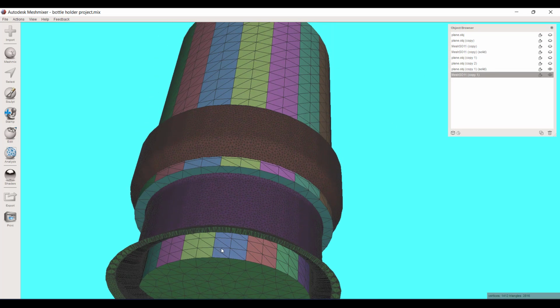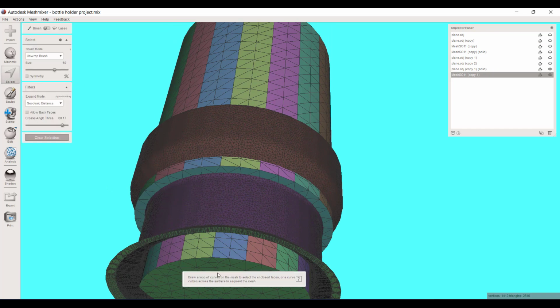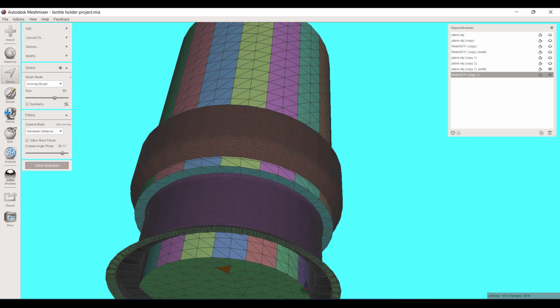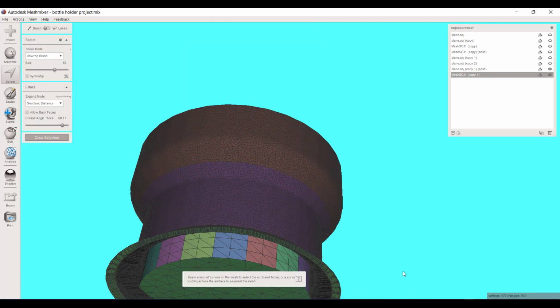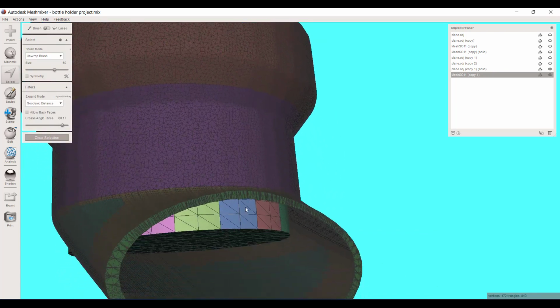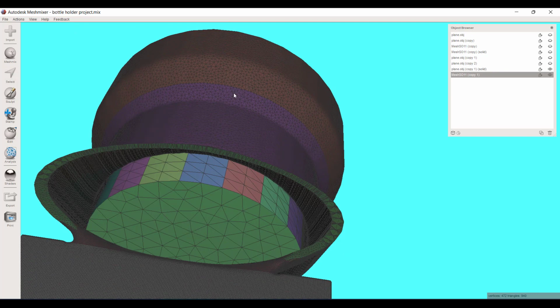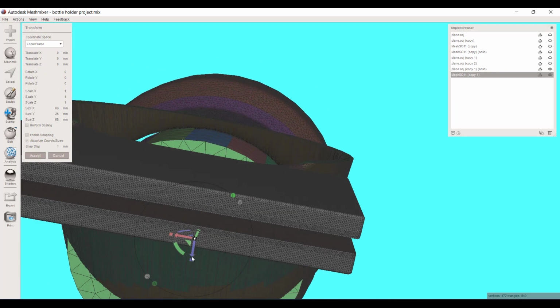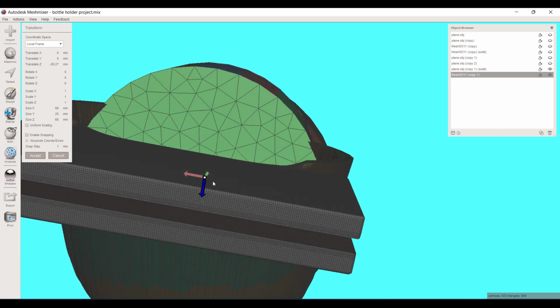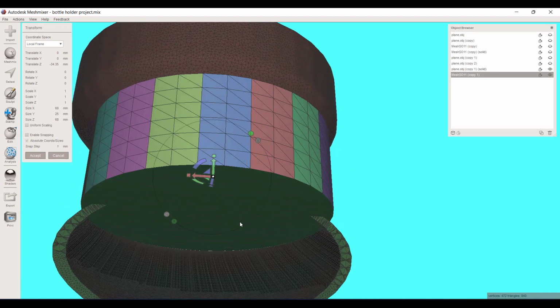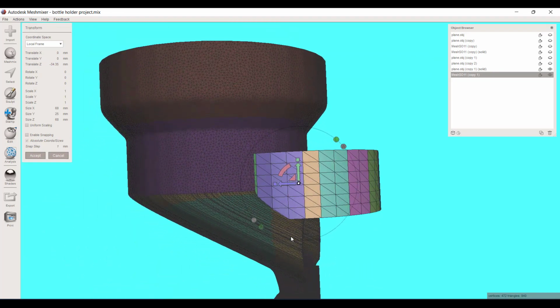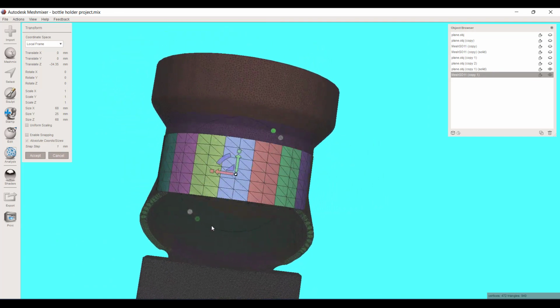Remember, this was the lid area and the bottle. I'm going to select just that and then invert and delete that portion. And what I'm doing is I'm just creating a shape that I can Boolean subtract from this to make that opening. So, and this will keep it all concentric again. So that I like.